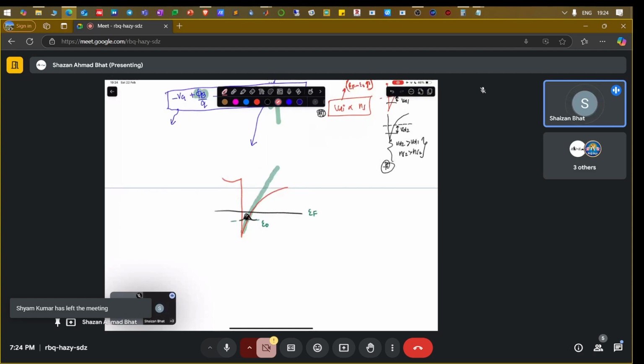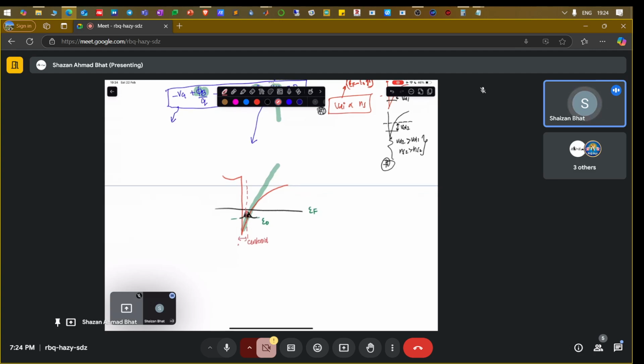Why? Because you have the charge which is present here, the center of this, which is the centroid. I talked about in this session that this distance is delta d, the distance of the centroid, where the charge density peaks, where the wave function of the electron peaks. The distance of its peak from this interface is delta d. Now you have this particular thing, which is the potential. Basically, if you have the potential, you have the electric field, and you can write this electric field as some q times charge density divided by epsilon naught. So basically, this is sigma over epsilon.